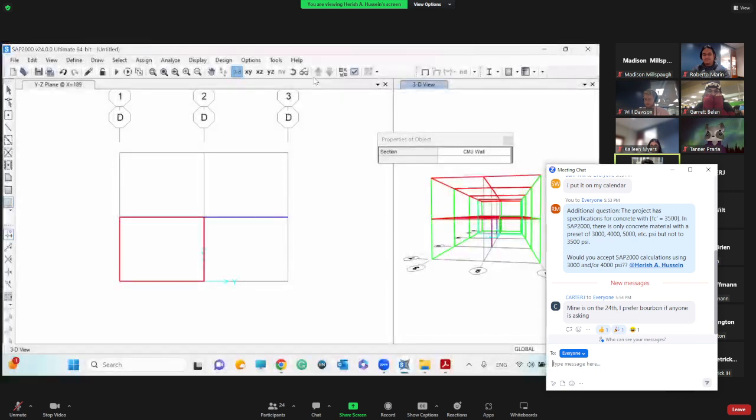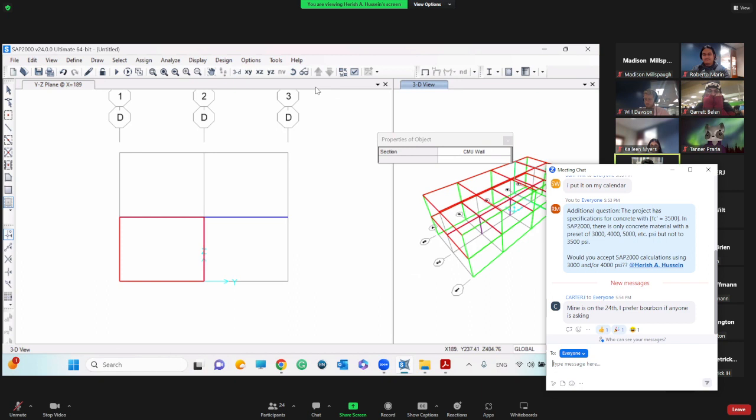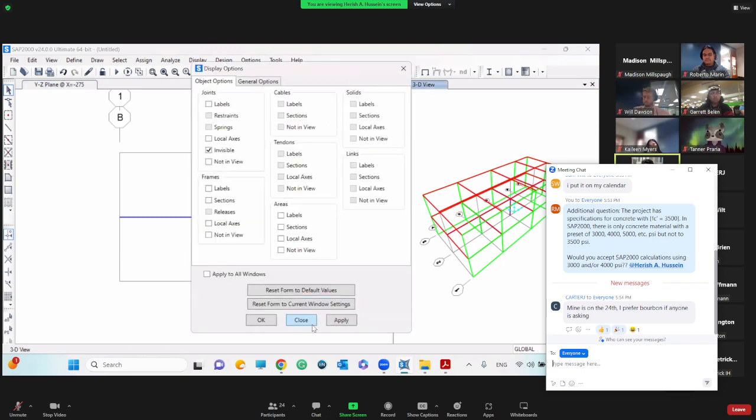Let me do a 3D. You gotta be so careful where you add the walls. I added one wall here in this panel and come here. Now we are here. We have one wall at the basement right here, which is this one. I add one wall here. See it added it here. Now I am done with the walls for the basement. Double check with 3D.